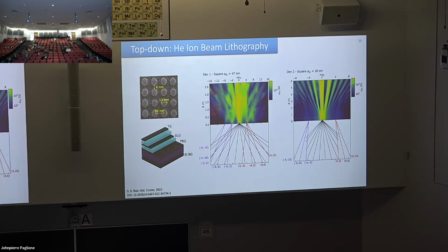And it turns out, even for this helium ion beam, it's actually a bit too aggressive. As you are knocking out atoms, you are inducing some disorder quite a distance away from where the hole is. You can see even in this image, this is not a nice ordered crystal. This is very messy and disordered around. So it's really hard to scale this down beyond the 20 nanometer limit right now.